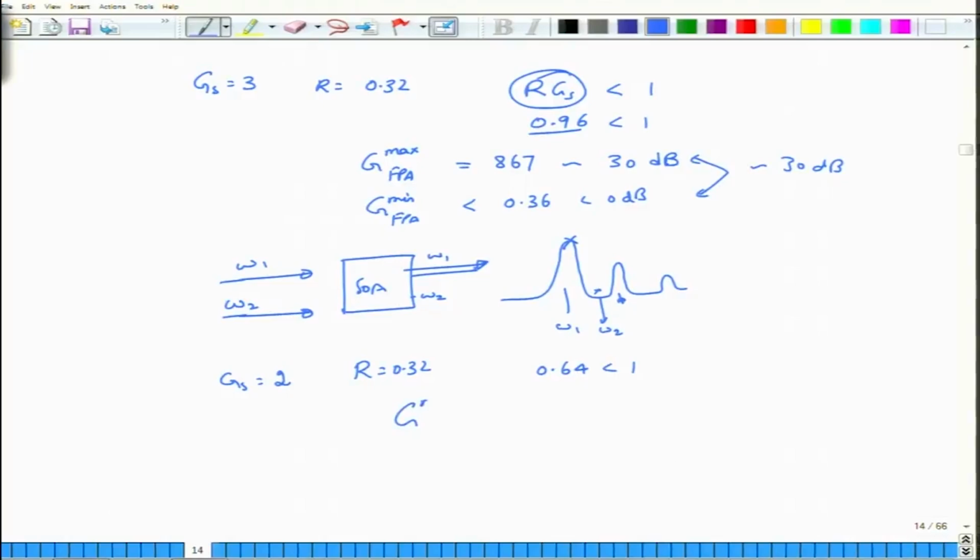but it turns out that the maximum gain, again you have to verify that these numbers are correct, okay, please do that, the maximum gain is about 8.5 dB. Okay, so this is 8.5 dB. The minimum gain is still quite less than 1, so the minimum gain is just about 0.32, but now you see that the gain ripple is down to just about 8 dB. So this is the ripple that you actually get, which is much smaller than this one.